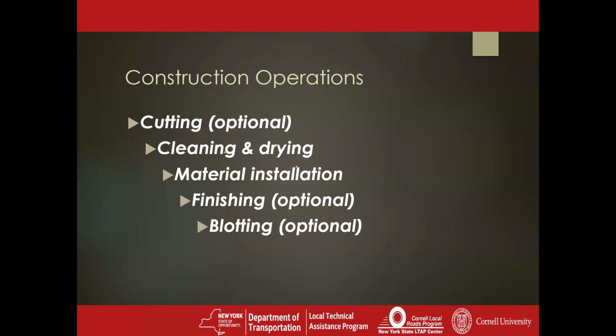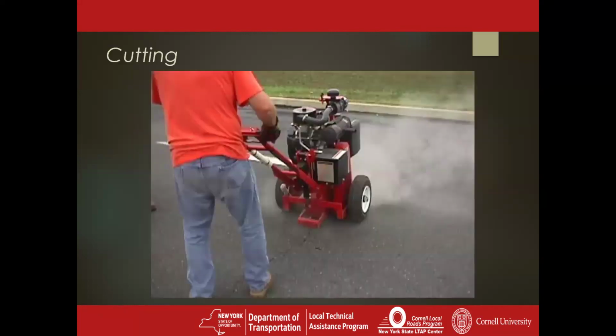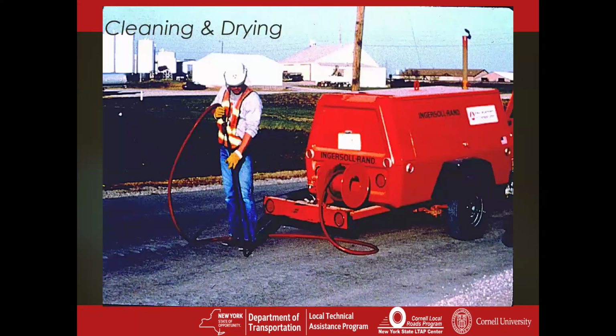In terms of the operations, pretty straightforward. Here we've got a picture of somebody routing in the crack. Gives you a nice channel. Cleaning and drying is critical.